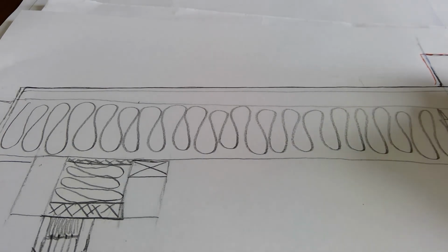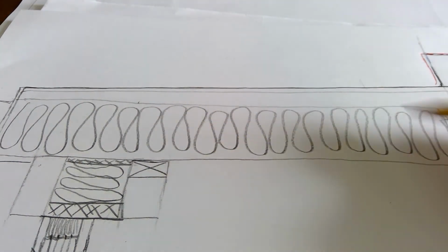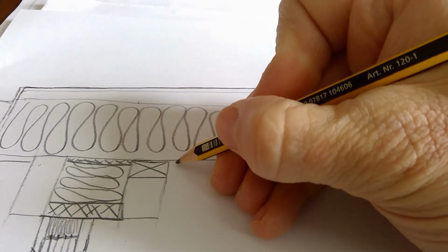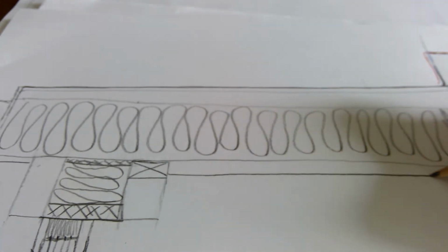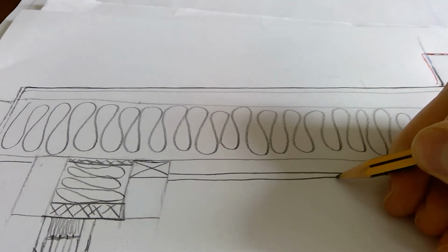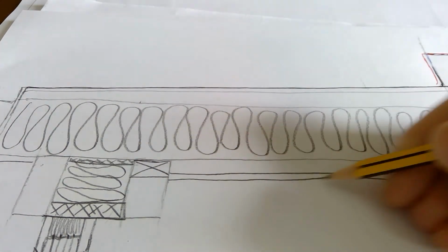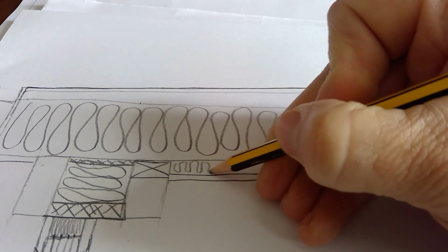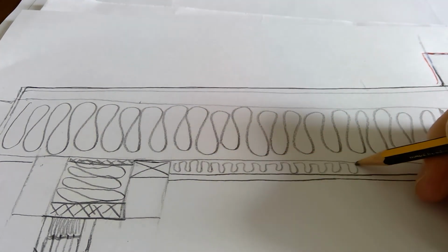And the question also specifies that there is insulated plasterboard fixed to the underside of the ceiling. That's the ceiling up there, the insulated plasterboard, 50 mil for the insulation, and there's your bit of plasterboard that's fixed to it, and that allows you to plaster the ceiling then, and that's also a layer of insulation, so there's plenty of insulation on that roof.